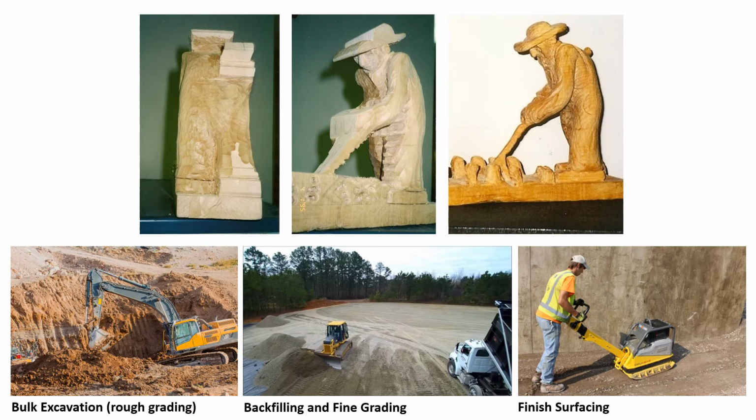And you don't have to remember any of this at this point. Okay? The key thing is to understand there are multiple surfaces and associated elevations that are necessary to correctly guide the construction process. What we specify in this class are finished elevations for the last step here. Okay, the finished elevations can be either for hard surface, such as the FFE for the buildings, or soft surfaces such as the ground outside of the building.